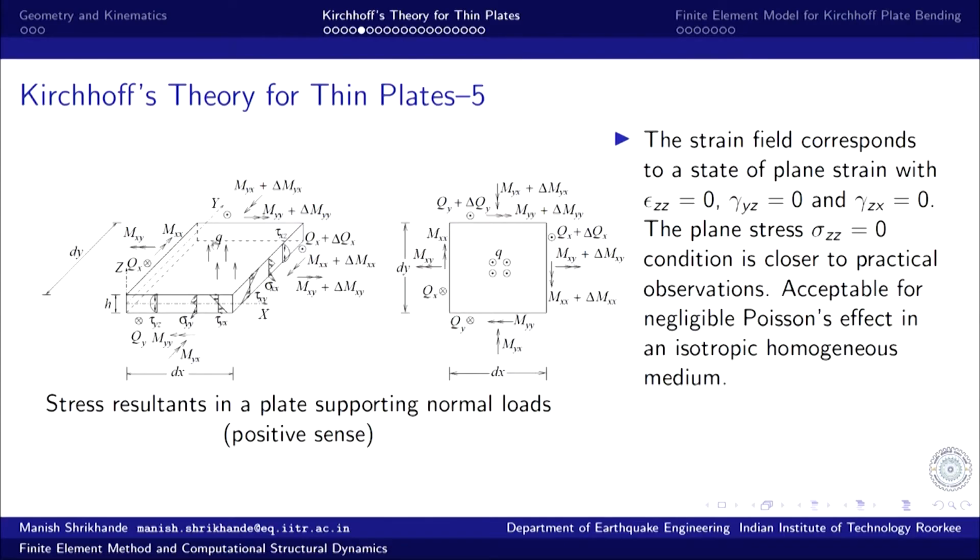However, plane stress condition is more closer to observations. The results predicted by the plane stress model have a better agreement with what we observe, but obviously it cannot be plane stress, because the normal surface is not free of traction. So, normal to the thickness direction we have forces here. So, it is not really a plane stress condition, ideally speaking.